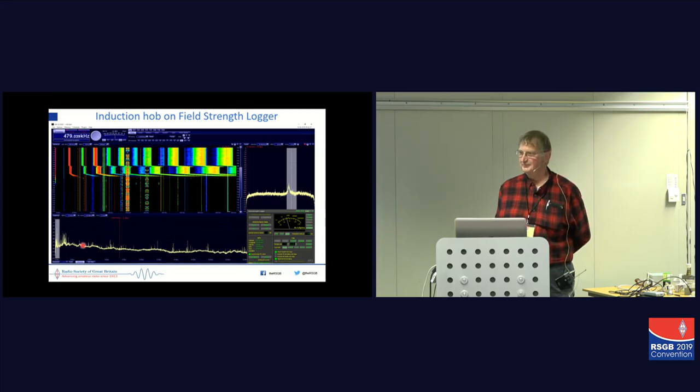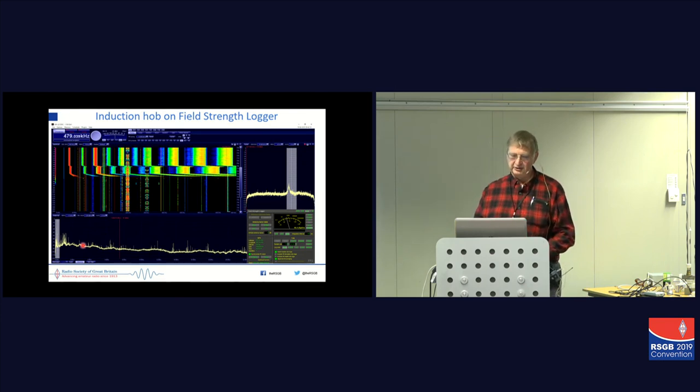So is that an inductive pathway? Yes? Inductive cooking? Yes. Okay. It's a domestic, boiling water in my kitchen. And we did this to take measurements to see how it dropped off, because we wanted frequencies around 70 to 80 kilohertz so that we could get an understanding of how they behaved as they went through a house. Guess what for? Wireless power transfer.